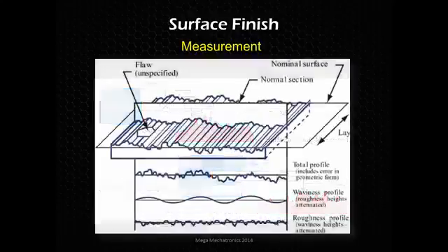So what a measurement would look like is something like this. Up at the top, if you can visualize, it's a section of a 3D part, but what we are measuring with the stylus is a 2-dimensional section of that 3-dimensional piece. And you see that flaw there, that would be like a discrete irregularity. There's only one of these in this part possibly, and that could be from someone dropping something on it and crushing that down or something like that.